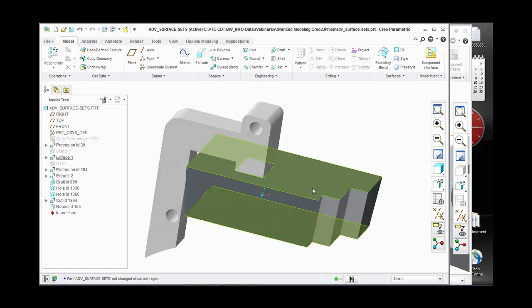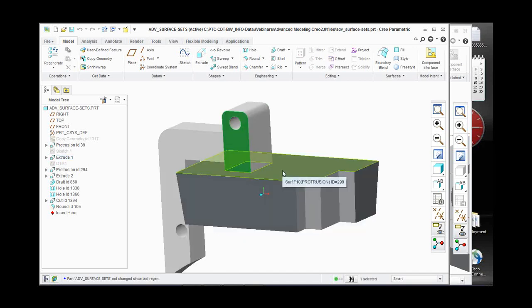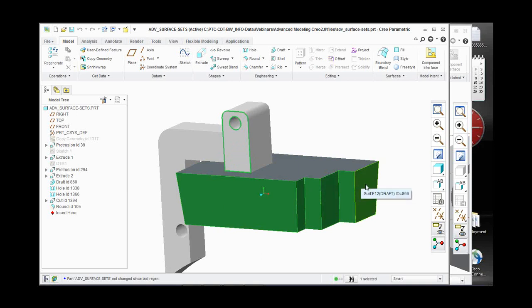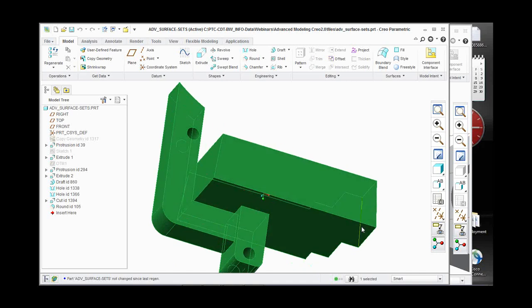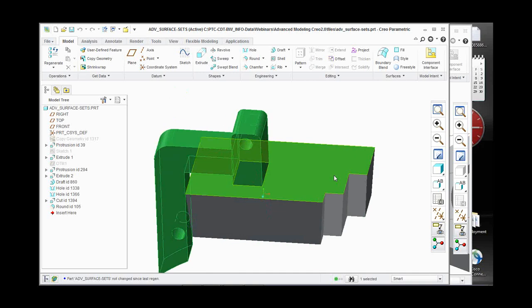Now, you can pick multiple boundaries. So for instance, if I pick this surface, not that you would do this, there would be a much easier way to do this, but if I come over here and hold shift and pick that surface and pick these all the way around, don't be afraid to let the shift button go. You actually can let go of the shift button and then pick it back up and continue to add boundaries in, and then there's the result. Okay, so just letting go of the shift button doesn't start anything over, it doesn't mess you up. All you have to do is go back in, hold the shift button again, because if you had to hold the shift button, you wouldn't be able to turn your model, because the shift button would be on, right? You wouldn't be able to use your middle click to turn the model.